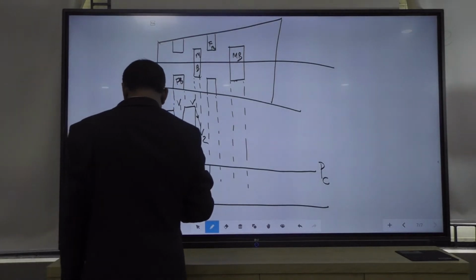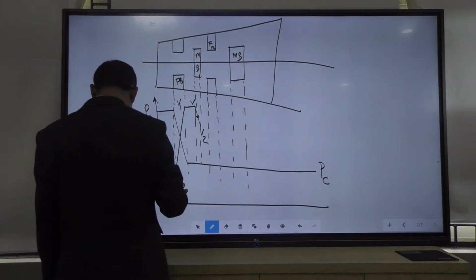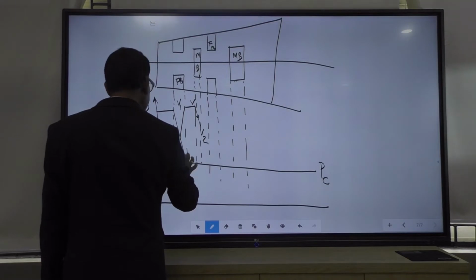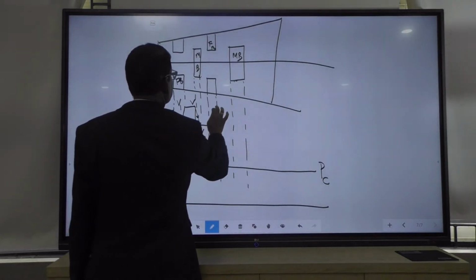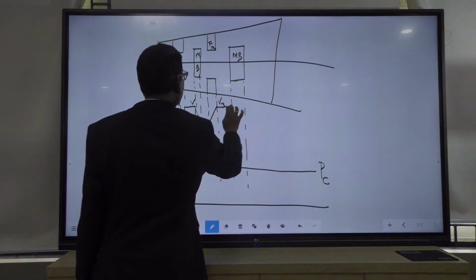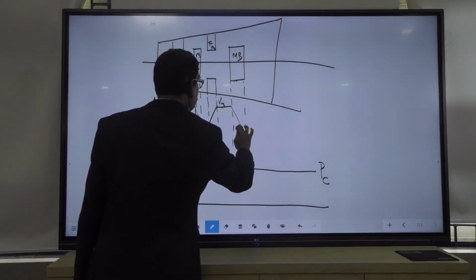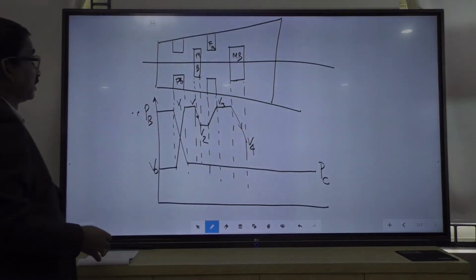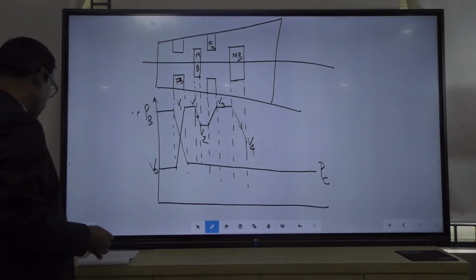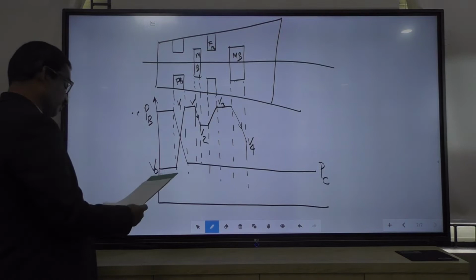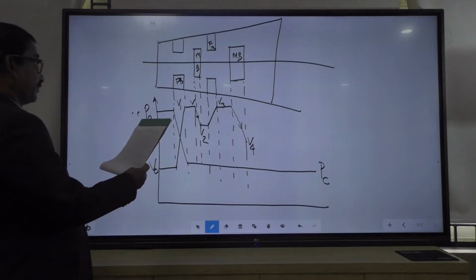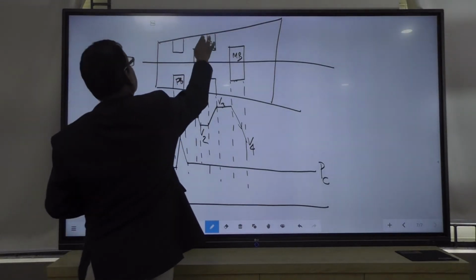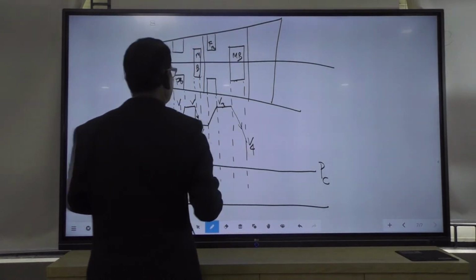Again this V2 in the fixed blade increases to V3, enters the moving blade, then it reduces to V4. So, that means here the velocity reduction takes place in different stages, different blades. Here we have shown two stages. This is one pair, fixed blade and moving blade, it is called one stage, this one stage and this another stage.